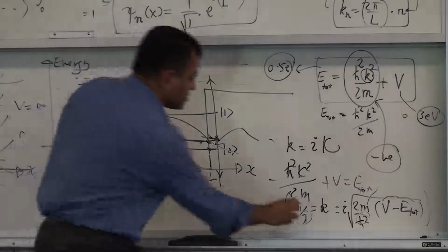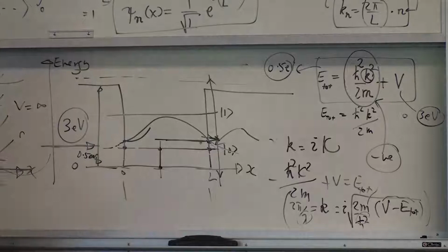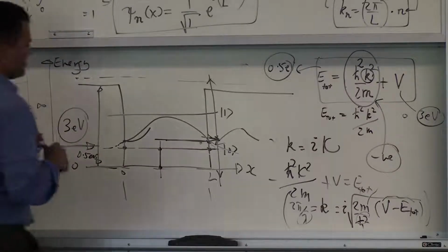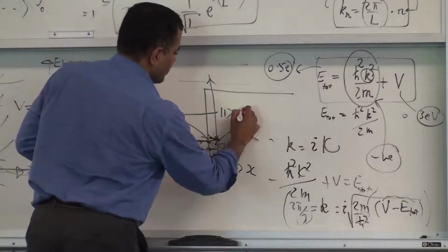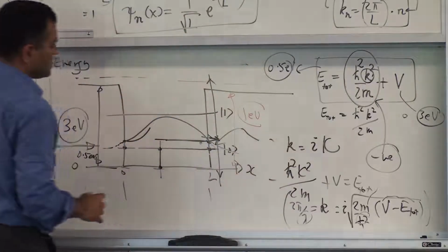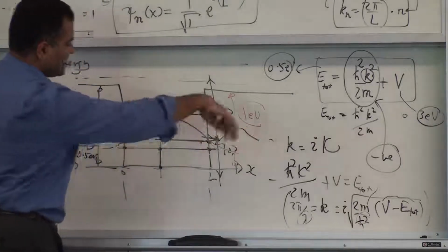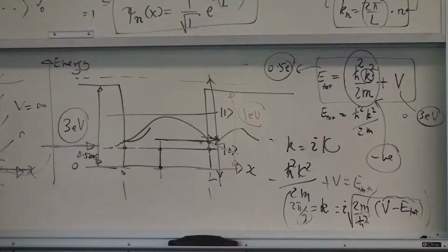So again, just to be clear, to summarize this, I think a good order of magnitude to remember is, if I have 1 eV barrier heights and effective masses of 0.1, the tunneling depth is about 1 nanometer. And that's a rough order of magnitude.